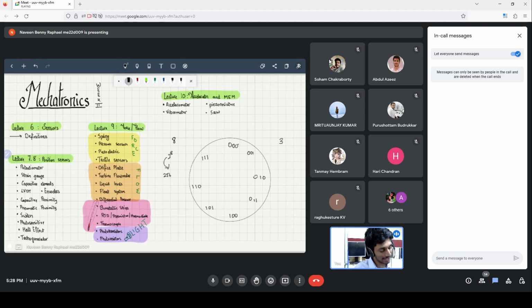However, say the wheel is spinning while we are taking this measurement. If the wheel is spinning while taking the measurement, we might read the first 0 from here and then read 1 1 from here. So instead of reading 0 0 0 or 1 1 1, we'll be reading 0 1 1, which is all the way on the other side of the wheel.